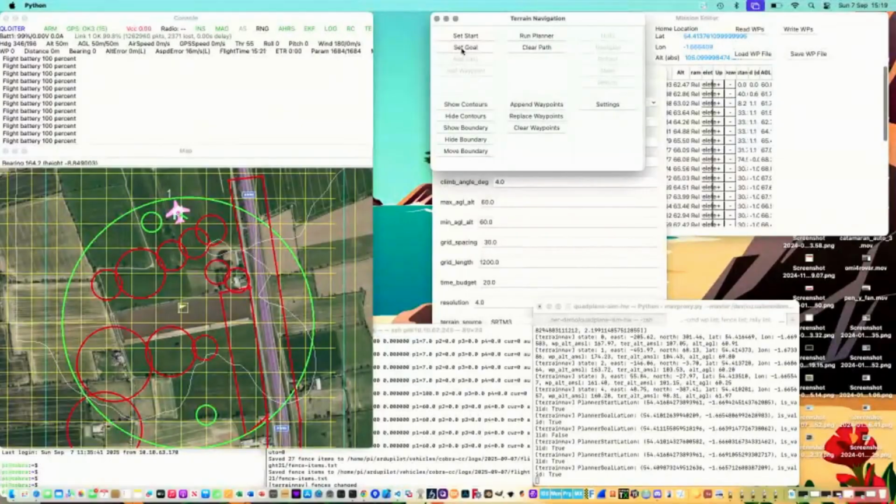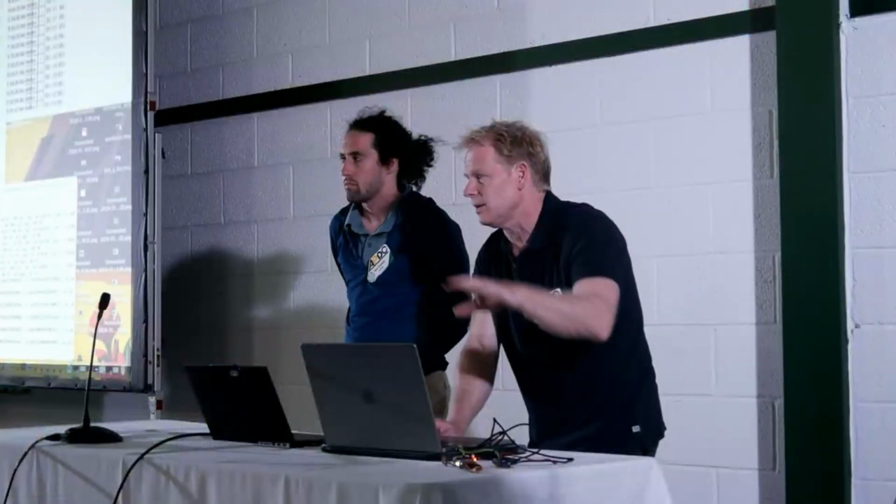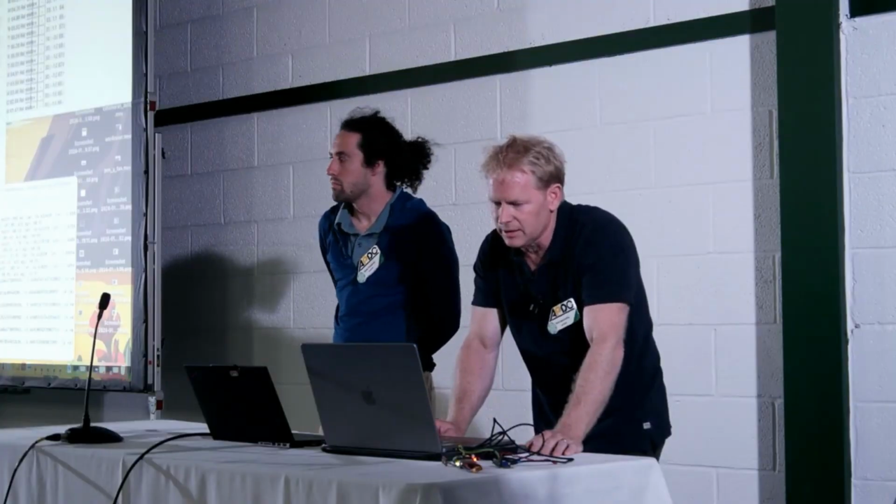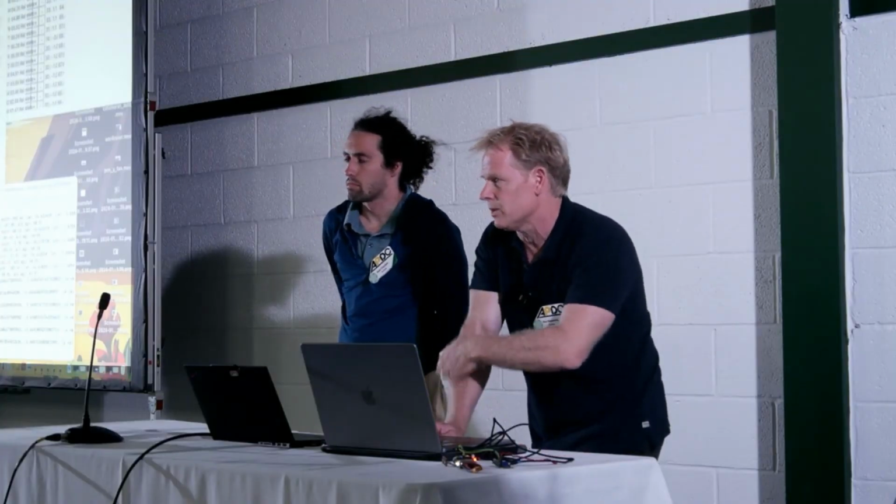Now, what we haven't done in the library so far, which is the hard problem, is when the plane fail-safes, it needs to find a safe place to loiter, and we would like to be able to do that on board. So the first thing that happens is the plane fail-safes. It goes into a planned return to land, and it needs to find a place to circle while it computes the return path. Now that has to look ahead in some sense, and it's currently an unsolved problem for us. And ideally, it would be done on board rather than on a companion computer.